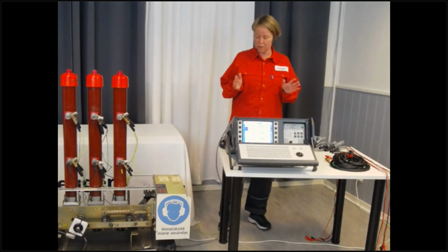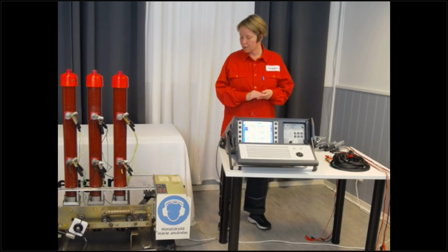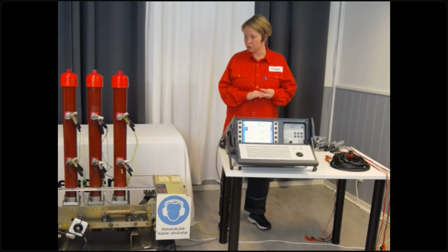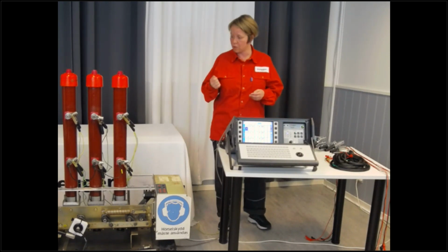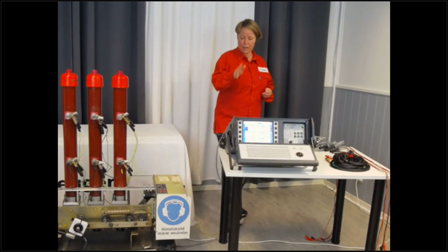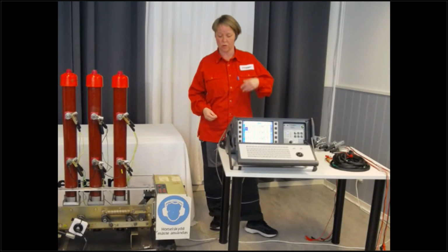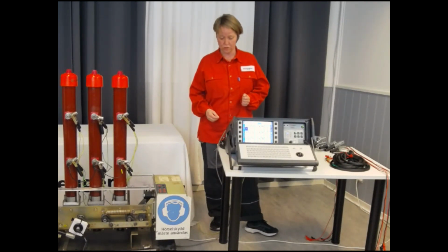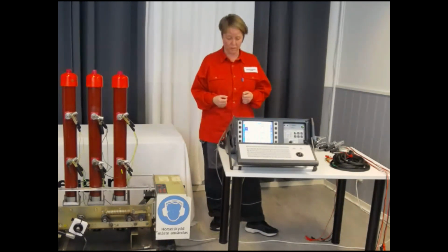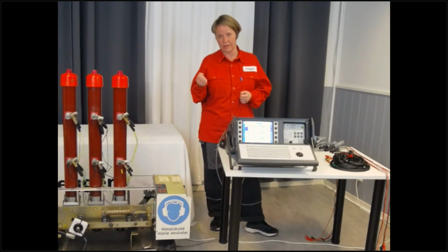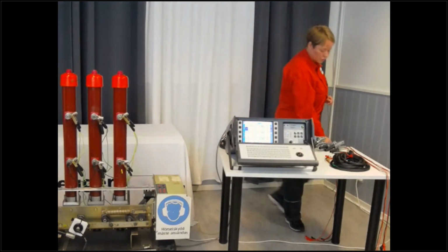So what I'm going to do now is start connecting the controls. And I'm going to measure, just like before, timing, coil current, and motion. With both Eagle and TM 1700 and 1800, the coil current is measured automatically by the control circuit. So when the instrument is controlling, it's also measuring the coil current. But the motion needs to be connected separately to an analog channel. So let's get started connecting again.